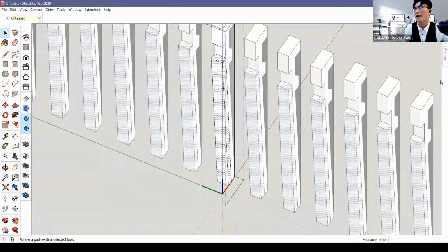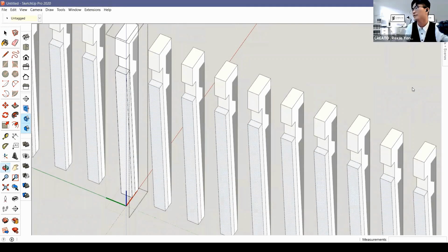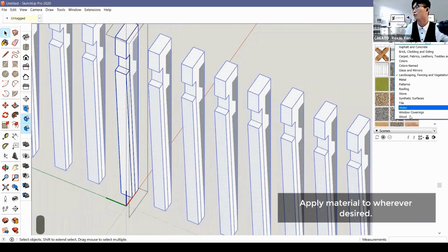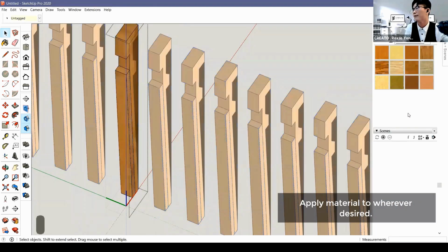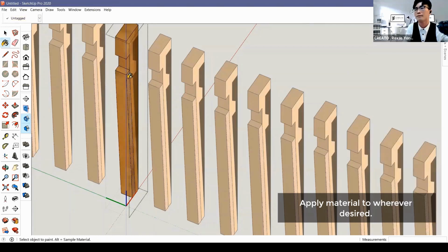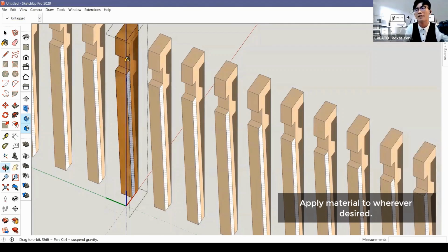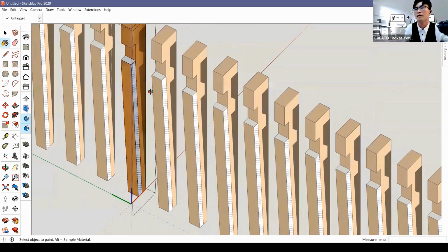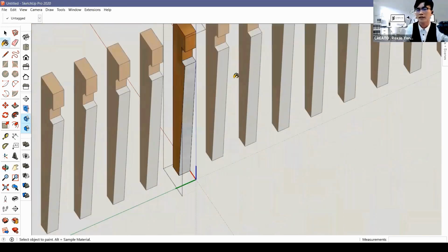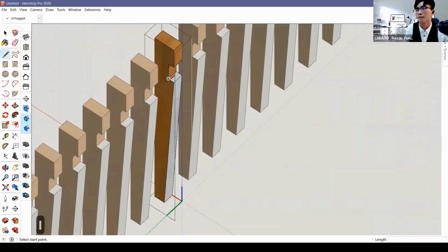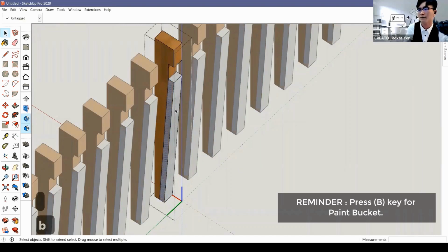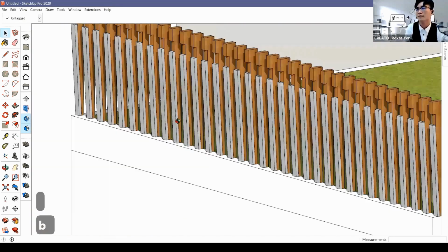All the surface, maybe I paint it with a timber texture. Go to wood and then timber. But this, maybe put some aluminium, metal, aluminium. It's going to be a cool color combination here as well. Maybe on the other side as well. Hit B, paint bucket. So this is my component railing.